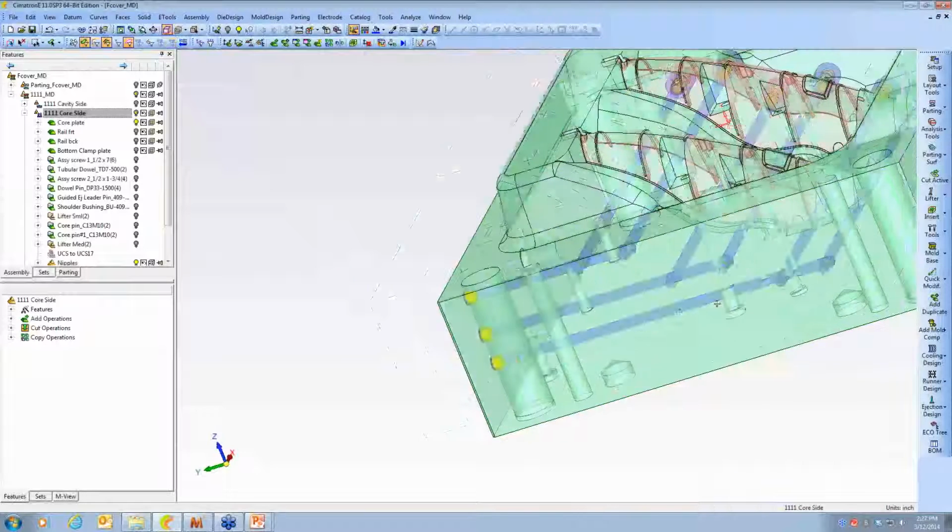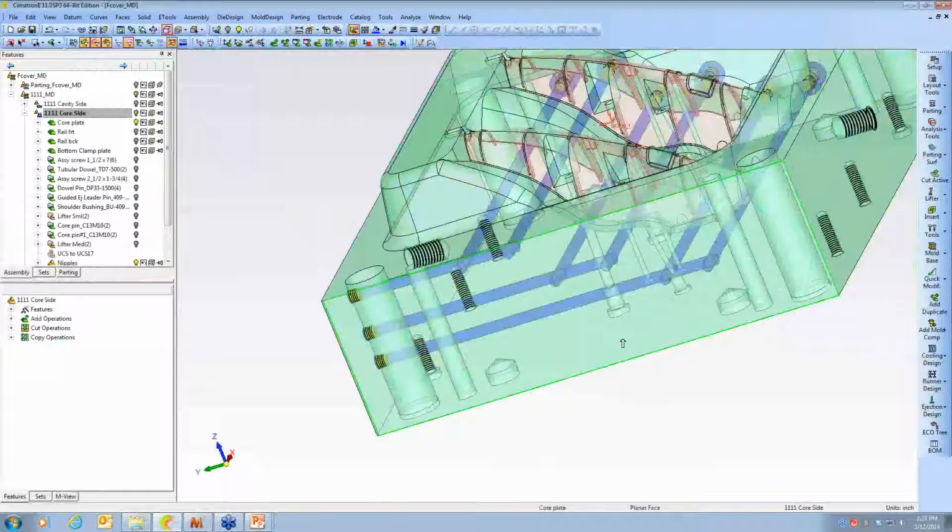So adding baffles is next. And the idea, of course, is to get the water funneled up near the part. In the past, this required a lot of time to measure and fit each baffle individually. But Cimatron has applied this same strategy of automating the hole depths into placing baffles as well. Let's take a look at that.